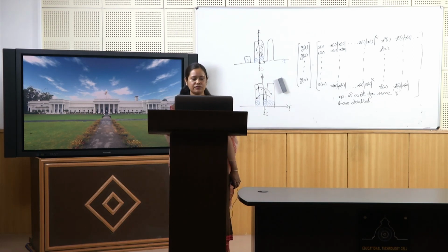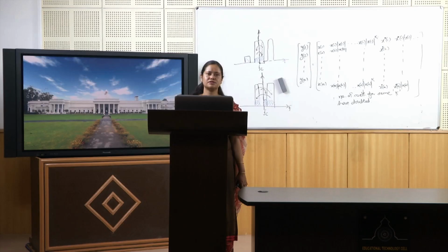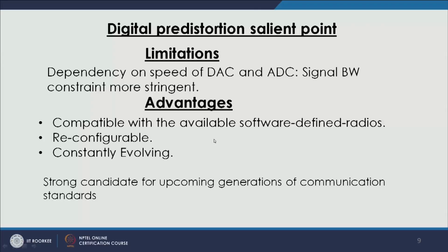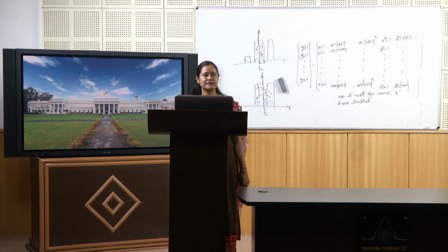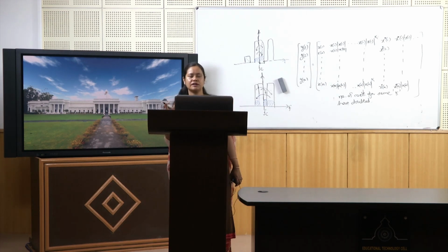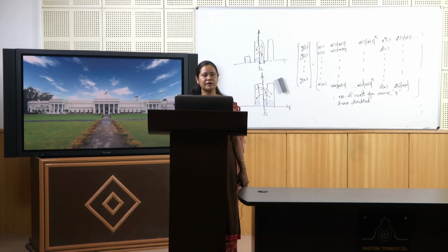and they are very attractive. For example, it is compatible with the available software defined radios, as we have shown in the demo, just by using small front ends and FPGA kind of devices. It is compatible because you are doing everything in the digital domain, supported by software. So, it can be ported from one place to another system easily, and because we are already using software defined radios for deciding the frequency and other parameters, we might as well use them for digital predistortion to remove the effect of power amplifier nonlinearity and IQ imbalance.